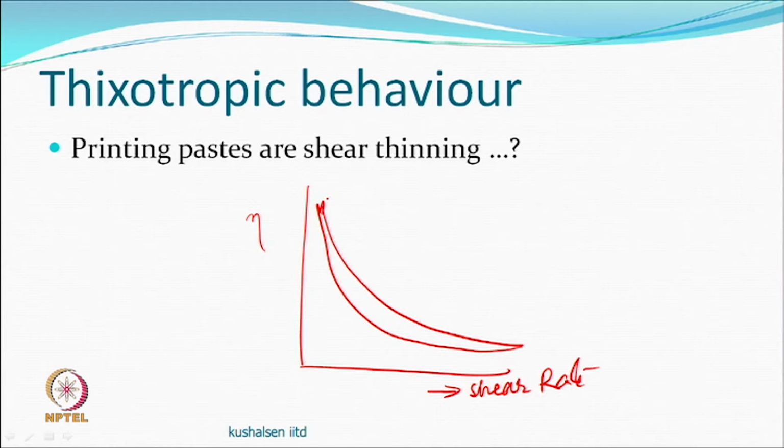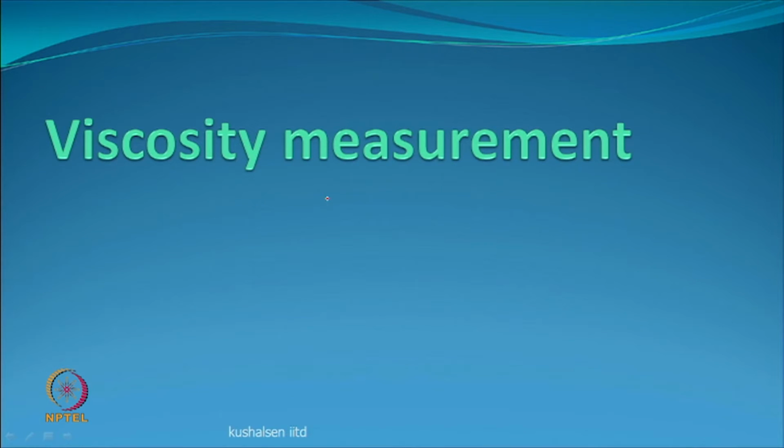So, that is the sensitivity towards this, but this sensitivity applies to every type of polymer that we would require for printing. This is not pH dependent, although we all understand viscosity is temperature dependent. So, if you increase the temperature, then things will be different. So, whenever you measure, you will have to say at what temperature you measured. Not only that, people will like to know how you measured.